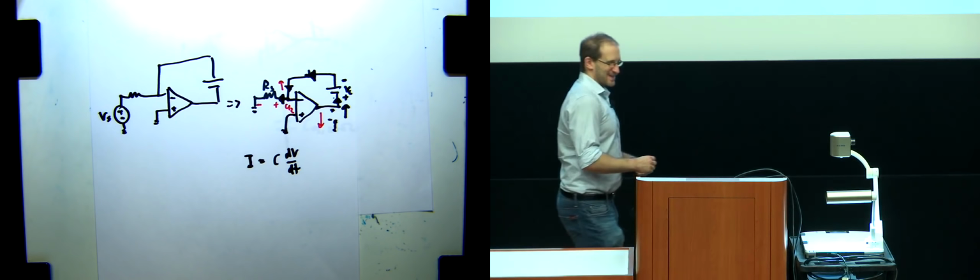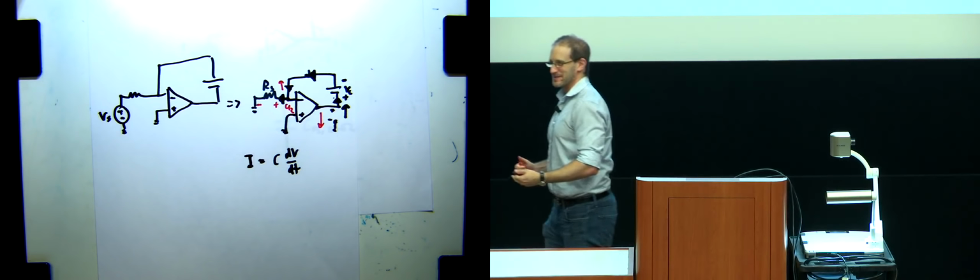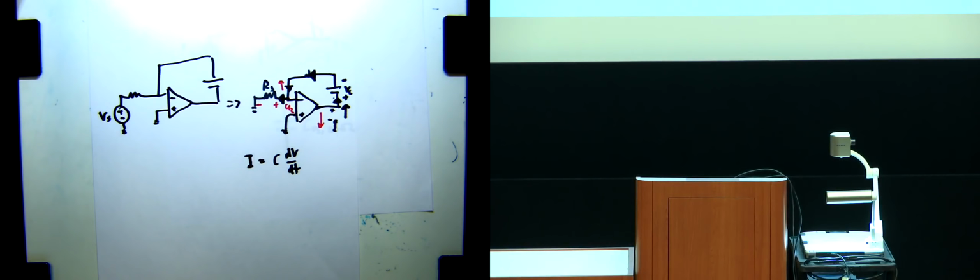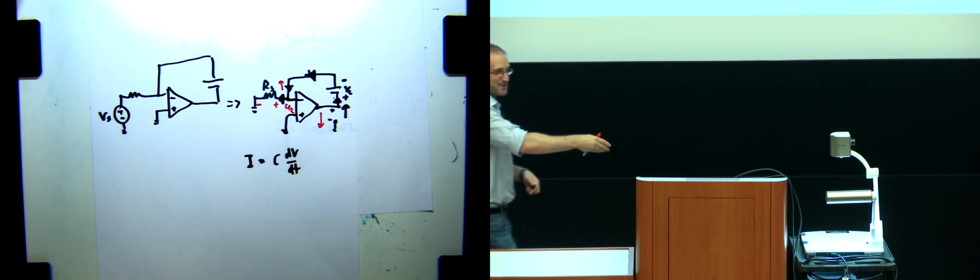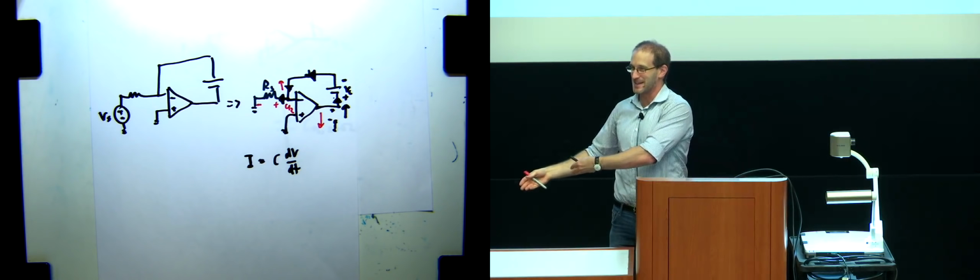Okay. So this is a good general question. Your question was, I'm a little bit confused because we said that in order for the whole thing to work, the top part, the U2 node here, has to be at 0 volts. But I just said that U2 is somehow changing and increasing and causing something to go back at the output. So remember, when you are checking for negative feedback, golden rule number 2 can't hold yet. Because you don't know if you're negative feedback or not. So when you're doing that check, you can't invoke that U2 is 0 volts, because you don't know that negative feedback has happened yet.